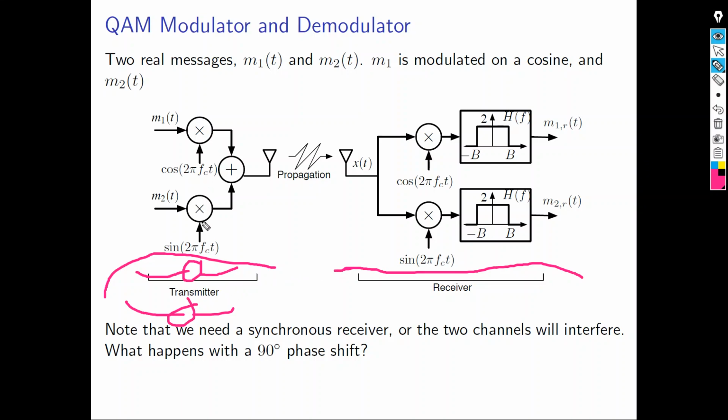I mean, orthogonal signals while using the same time, same frequency. Yes? And they are orthogonal to each other. They don't cause interference to each other. If you can come up with another carrier beside cosine and sine, which can be orthogonal to sine and cosine, then you will be the second genius in communication systems. Yes, you understand me, the importance of this research area.